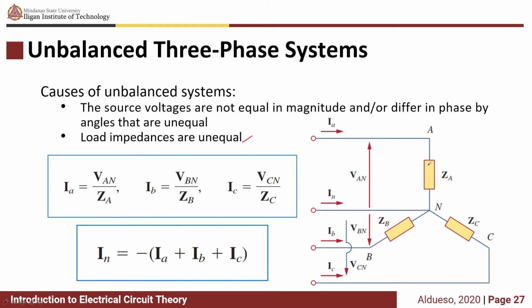If you have, for example, an unbalanced Y load with a neutral line, solve for the line currents. You need to apply KVL at these loops, these equations. And for this case, IN is not equal to 0. So there is a current flowing through the neutral line.